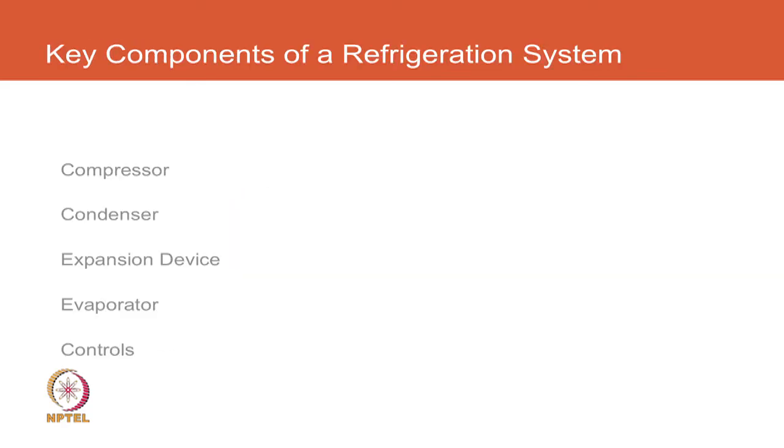So, we have looked at these components, and the thing that is missing now is controls. We design something for comfort, and what happens when the temperature is attained? We need to either regulate it, slow down the capacity, switch it off, switch it on again. So, it is an integral component of an air conditioner. For reliability, we need to take care of situations when the condenser is clogged, the pressures go high, the compressor can fail.